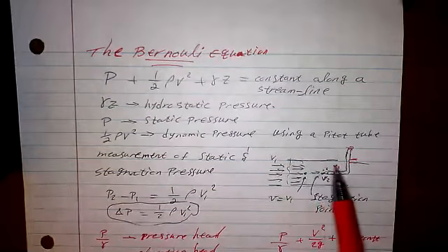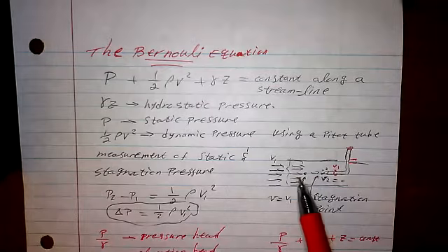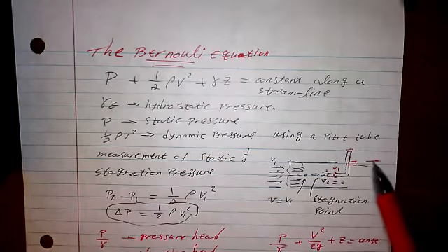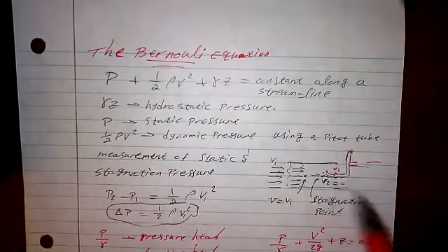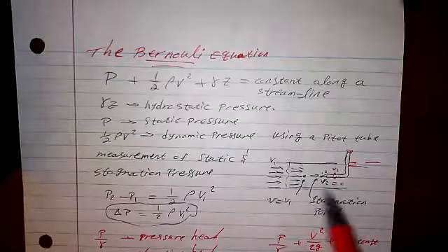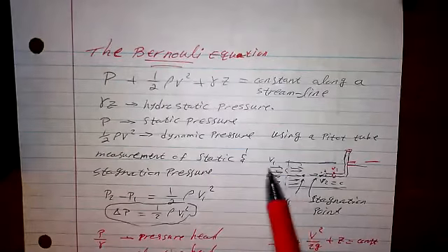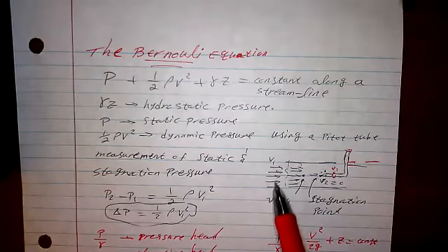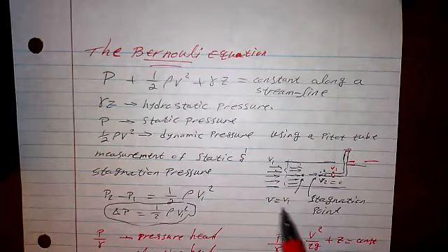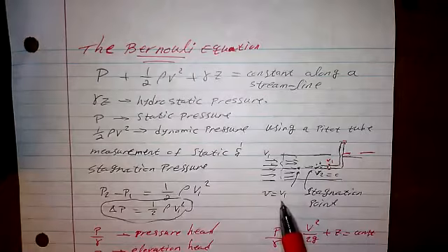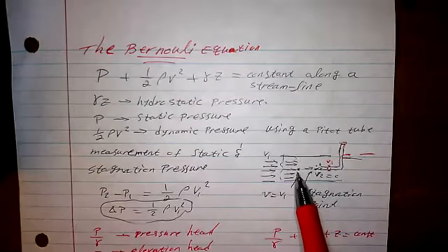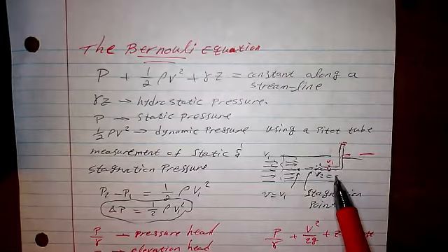And when we have a pipe or conduit, a round pipe or square pipe, we insert the pitot tube. There's a hole in here. You insert it there, and it will be perpendicular to the flow that is coming toward it. Okay, and then when you have this air velocity, the inlet velocity, a velocity profile, we have a point which we call a static point, and V equals V1 at that point, and at the nose V2 equals 0.